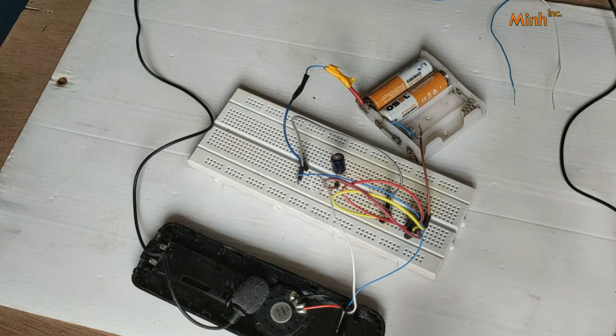Yes. Okay, so it is taking time to charge the capacitor. Discharge is quicker, because it is discharging through a 10 kilo ohm resistance. But charging is through 330 kilo ohm, and since it is a 10 microfarad capacitor, it is noticeable that it is taking time.